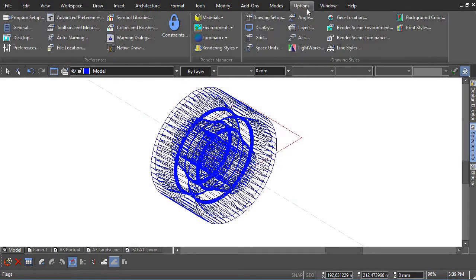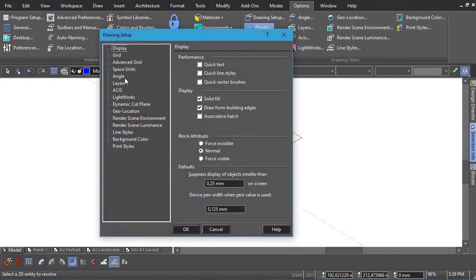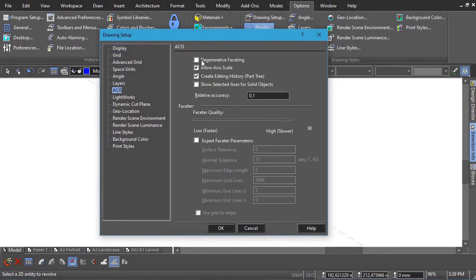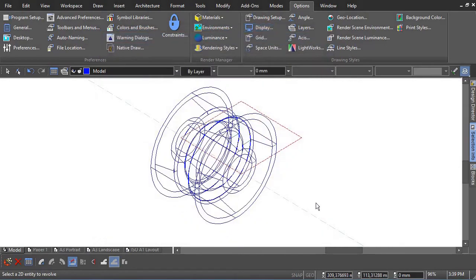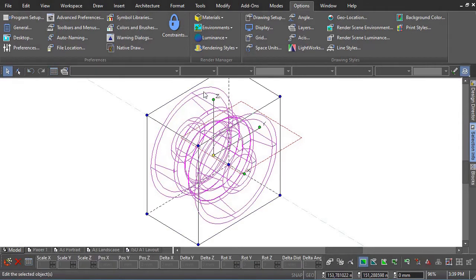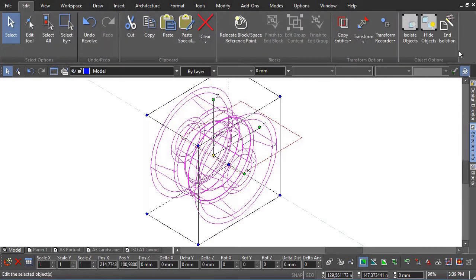Apply the following options to reduce the surface lines of the new solid. Use the Isolate and Hide Objects option on both the profile and the solid.